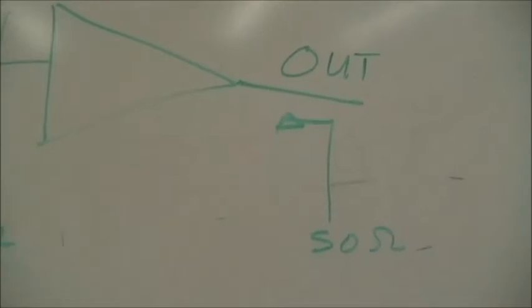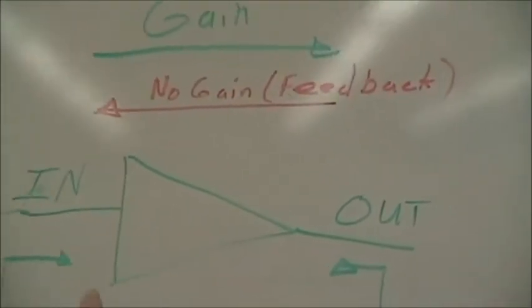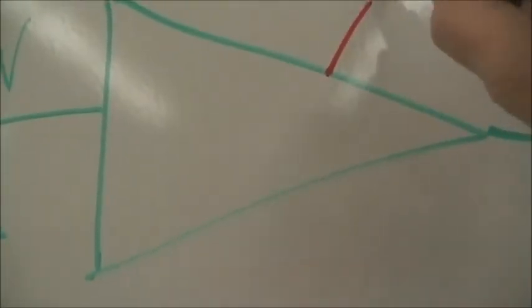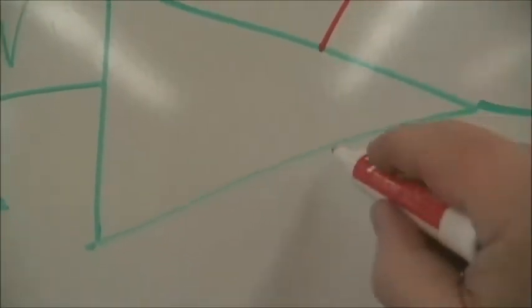So for the last measurement, at least in this lab, we're going to connect an amplifier to the network analyzer. Now we know what an amplifier does. It provides gain from a forward path to the output, input to output. Of course, we must have power supply. In this case, this is a 15-volt amplifier.